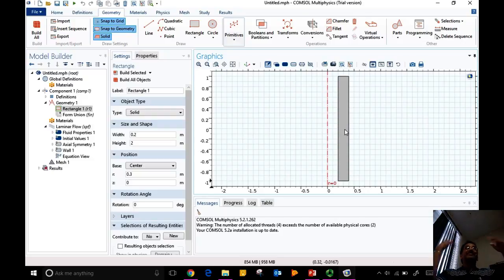Good question. Please keep raising these questions. Okay, that's an important question. Just because the geometry is vertical, that doesn't mean gravity is in the vertical direction, right? You can put the gravity vector any way that you want. So when you have g, you're going to give 3 numbers, which are components of the gravity vector, and each component will be added to the respective component of the Navier-Stokes equation. Okay, so you can do with respect to gravity any way that you want by simply putting the gravitational vector, but this is the axis that it picks arbitrarily.